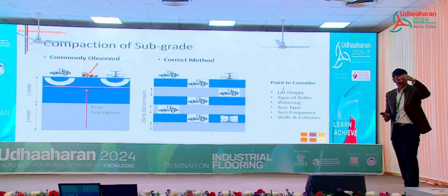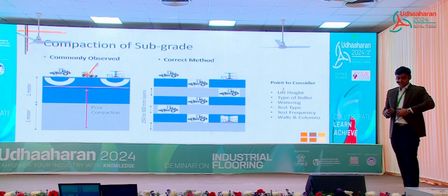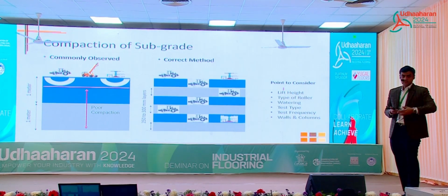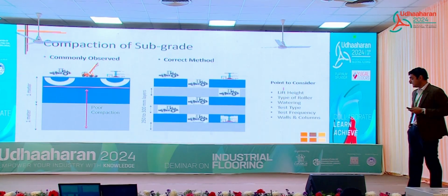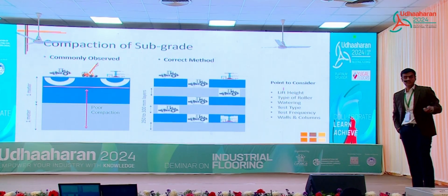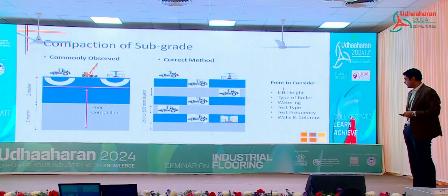You do not need to actually involve a geotech consultant, because that slows things down. The guy will test, make a report, and it takes a week. Two unskilled guys can do that rapid moisture test at site. It's like a 4,000 rupee kit, and that can save you a lot of trouble later.